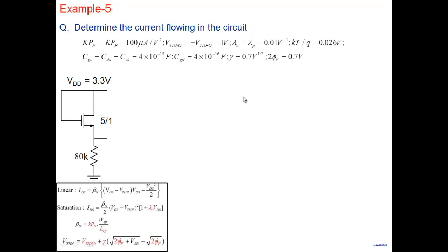So here, as I said, a series of simple circuits. Let's start with this. Here is a MOSFET connected with gate and drain shorted together, with the resistor put here, and we are asked to calculate again the current. Once you know the current, of course, you know the voltage here. Now, anybody sees a problem here?